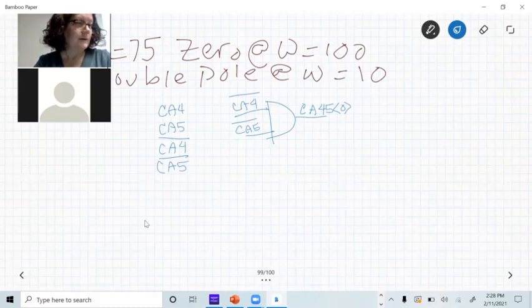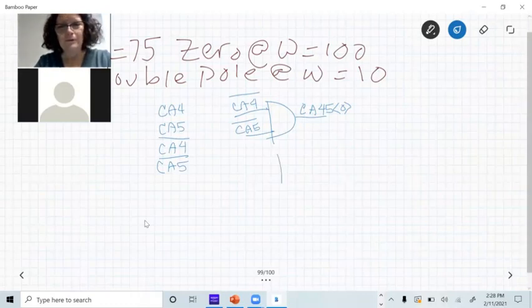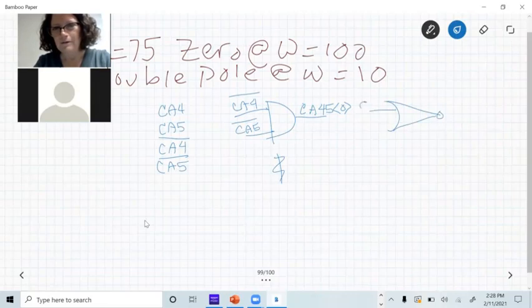Right. And you could build the AND gate by building a NAND and an AND with transistors, or you can do what one student did, which is do the De Morgan equivalent and invert the inputs. You could do this also. This is equivalent. Not the inputs.